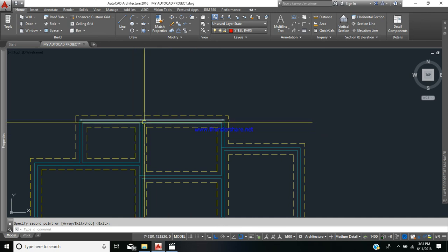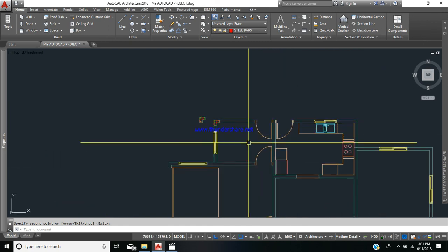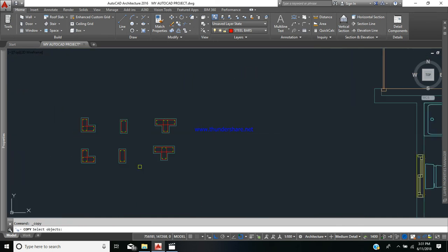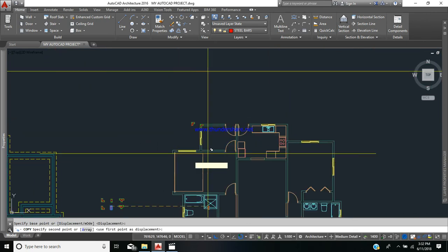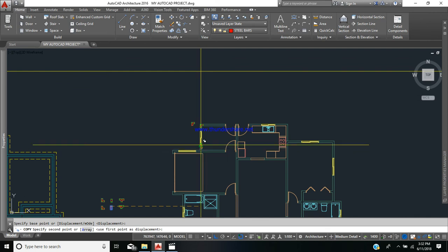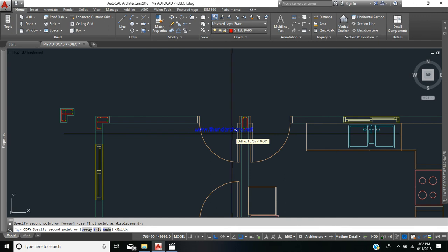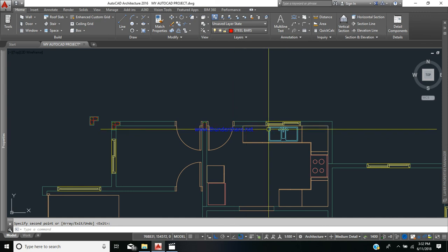But you can be misled because here it seems as though we could have taken a T, but the floor plan would indicate that at that particular intersection, a T would not be appropriate. And so I'm going to be copying one of my I stiffeners, which is this one. I'm going to be holding it here, based on the fact that I would want to terminate or paste that at this location. Alright, and so we would have gone about the building installing stiffeners in a similar way.